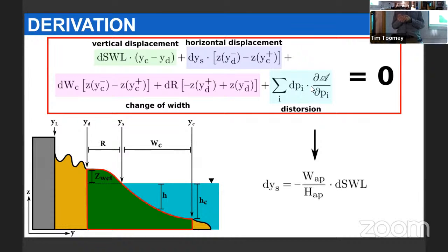Okay. But this settling velocity already includes these factors, kind of. You have a settling velocity as an empirical measurement, and that's good enough, I think. Usually the parameterizations available are based on settling velocity. So if there are other effects that are not considered, they are subsumed in this parameterization. It's also good if your model doesn't contain too many material parameters, because you have to determine all of them. And if settling velocity is a good one that includes everything you need, it needs to be calibrated somehow.